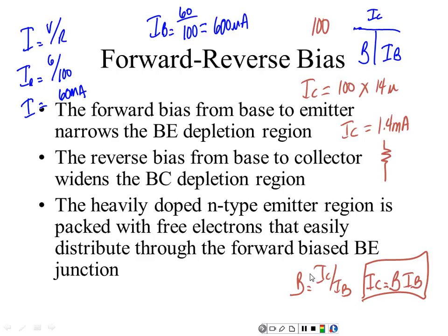So if you measure between the collector and base, then the collector and emitter, you'd see that the difference between your emitter and base is only about 700 millivolts. So if it's dropping 5 volts, that 5 volts is being dropped at the collector. So that means the collector junction on a transistor is the hottest junction. So if I'm going to expose one of the leads directly to the atmosphere, it's going to be the collector. So we'll get into these cases like this. This is a TO-220.